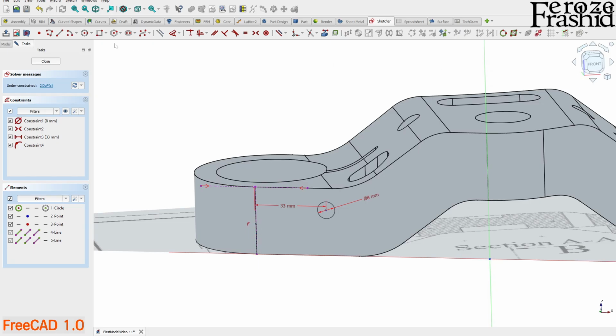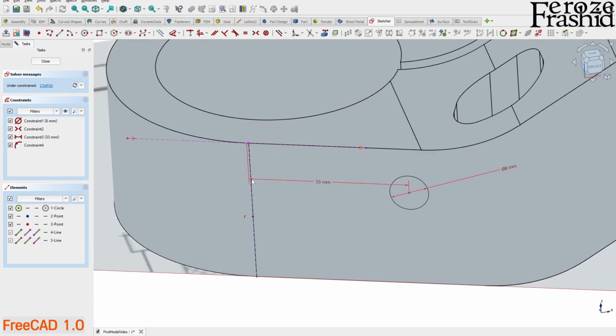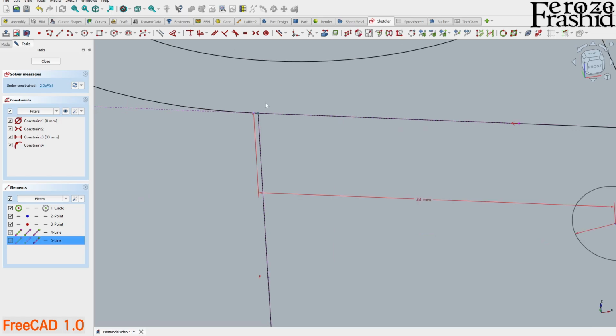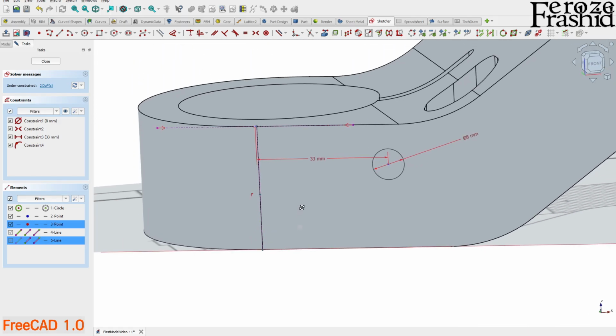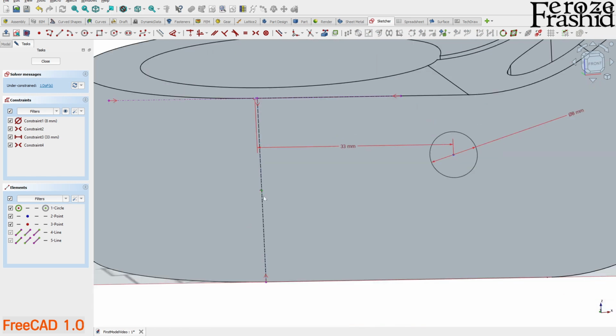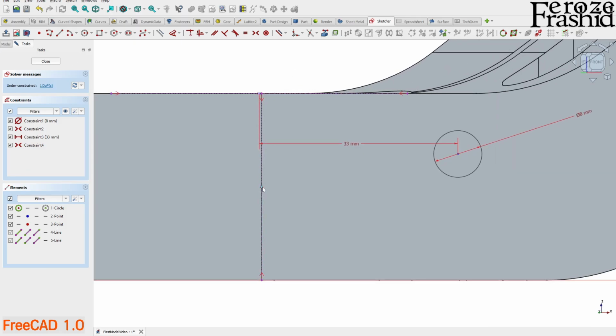So what I want to do is find that manually. Take this point, not this center, the point on the line that we just drew, and then take the lower point and the middle point, since we want to place it in the middle. So sequentially, the two ends first and the middle one, and hit S on the keyboard. That places it in there. So that's also how you apply symmetry by default. The first one we chose to get the suggestion, and the second one we found ourselves.